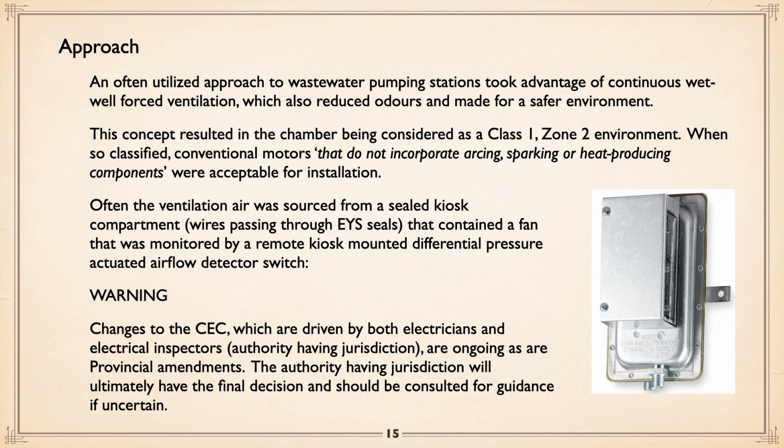An often used approach at wastewater pumping stations is to take advantage of continuous wet well forced ventilation, which, number one, reduces your classification down to class 1 zone 2 environment if you've done it right. But it also reduces odors and generally makes for a better environment.